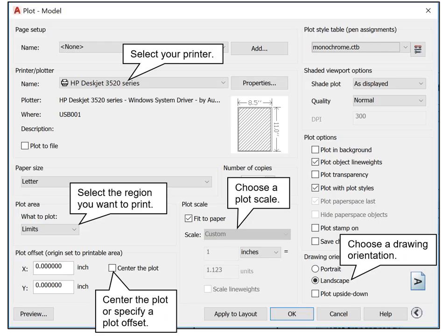Now the page setup and the print setup is essentially the same. It looks like this. This is the dialog box that pops up. If you have a defined page setup, it'll be right here because you would have a setup that you saved. But if you just hit print, it'll pop in here. There won't be any page setup, and then you've got to answer the various questions. So you've got to say, what's the printer I'm going to use?